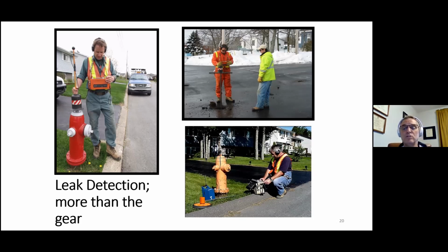Okay, and sometimes this is used to find the real small leaks or the difficult leaks where there's a lot of background noise and you're competing with other noises in the neighborhood, things like pumps and transformers. These come with filters, basically artificial intelligence that recognizes the noise for what it is and filters it out so you can clearly see what you're looking at in terms of leakage, and then it pinpoints the leak where to dig. So these are the two most common technologies that we see right across the world. This is the first one we started with, the evolution of the so-called listening stick, and this, of course, is the new methodology that has really come into play in the last 20 years.